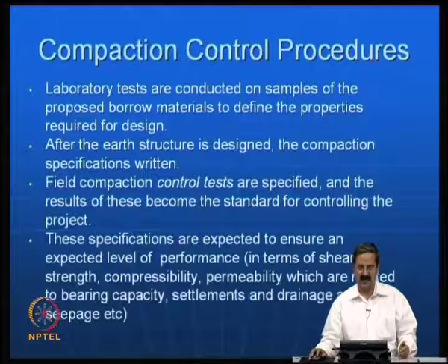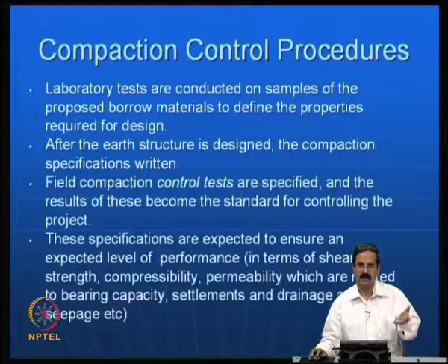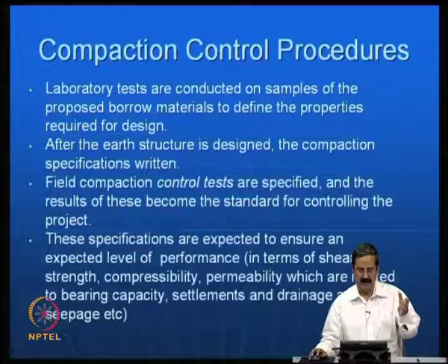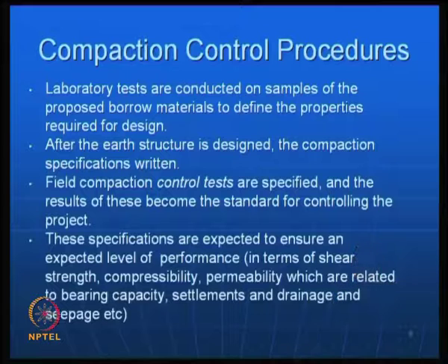So essentially you are trying to replace some amount of expansive soil with a non swelling soil and then see that it is all right. So the properties of that non swelling soil are very important here, and we have some specifications for that. After that, the pavement structure is designed. Say for example you design a pavement where the CBR of the expansive soil is some 3% or 4%, and there are some methods which will tell you how much thickness of cushion is required.